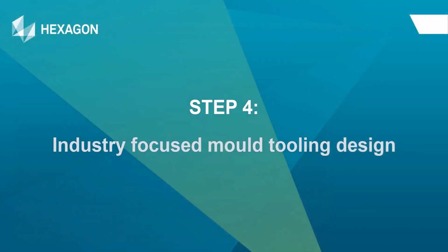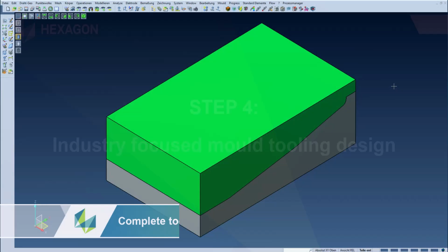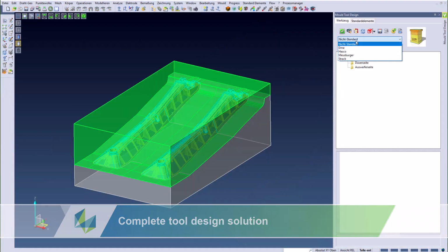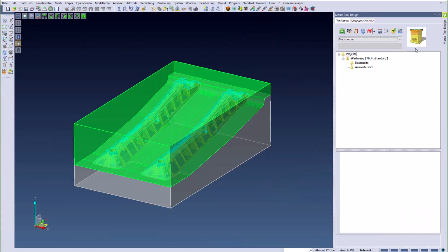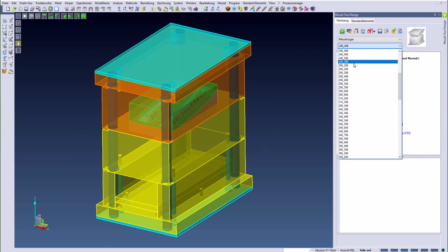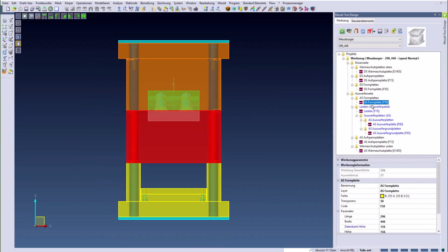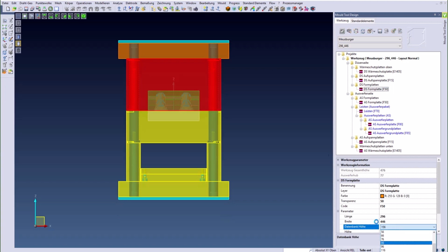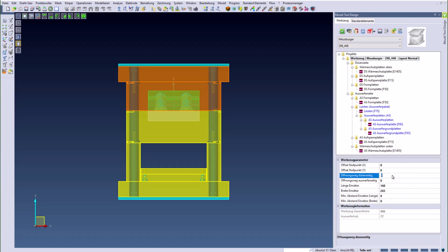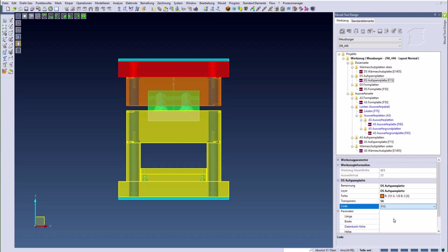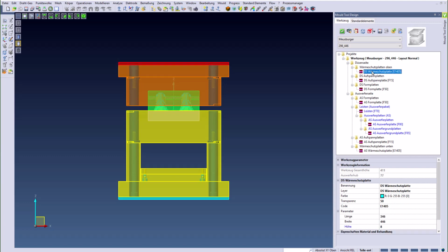The mold base is the main part of a mold as it provides the structural framework for the high-pressure injection process. It is assembled from diverse steel plates and parts and is readily available worldwide from standard suppliers. Typically, selecting an appropriate mold base for manufacturing a plastic part involves considering the number of cavities, insert dimensions, runner size, location, sprue, and gates.